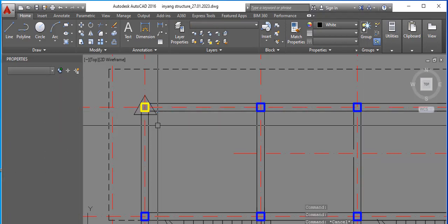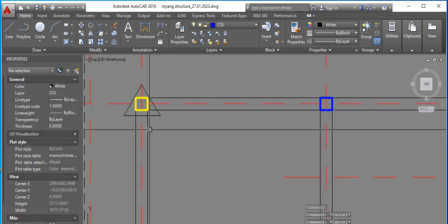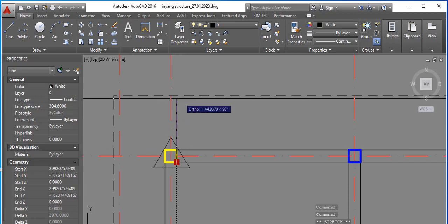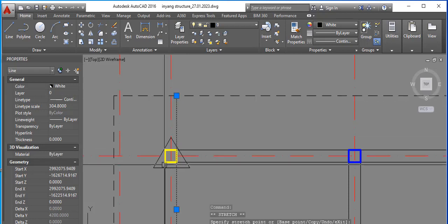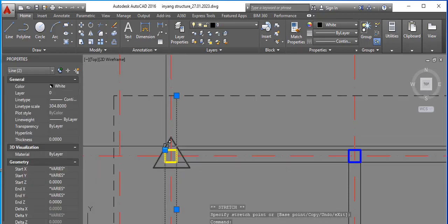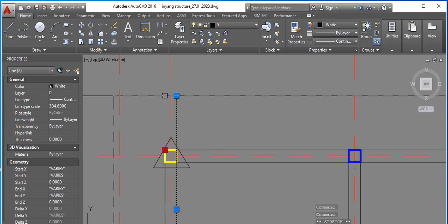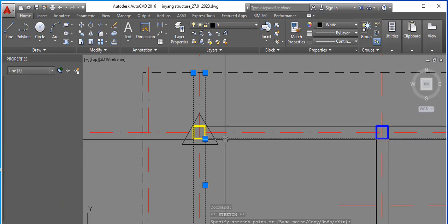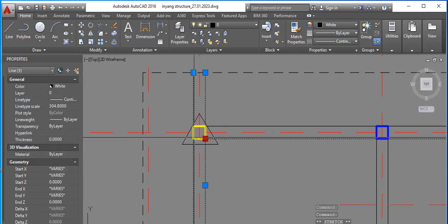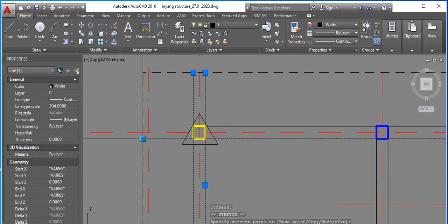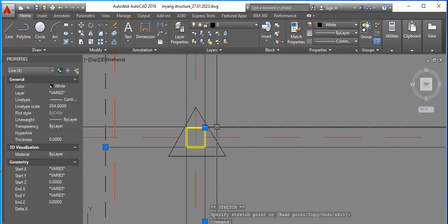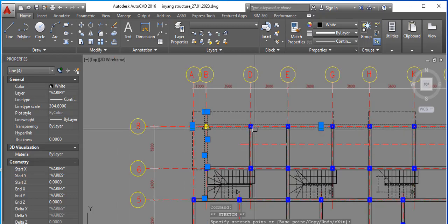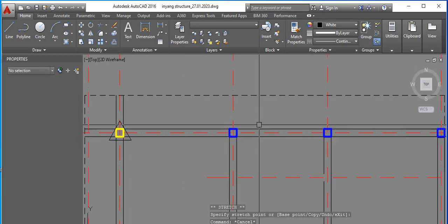I like using beam cantilever because it has more depth to carry the loads than slab cantilever, which is just 150, but the beam could be 450, which is better for me to carry the cantilever. So I will extend all this to this part, all this to this part, and this is what I will do.